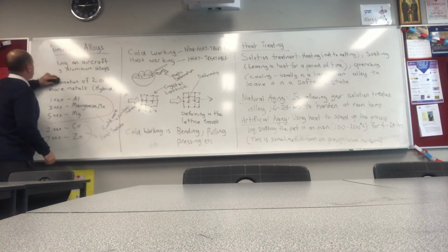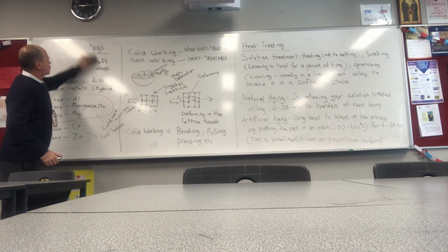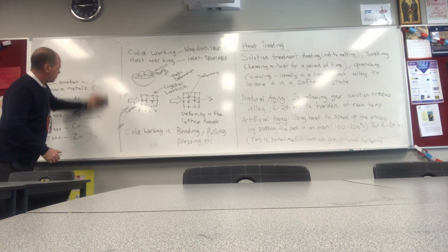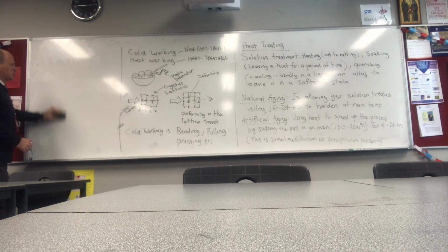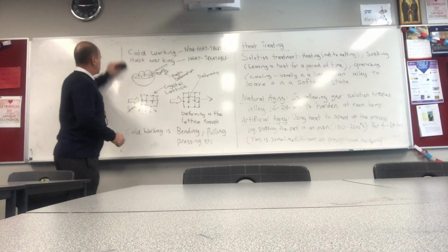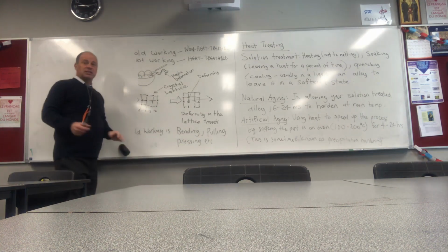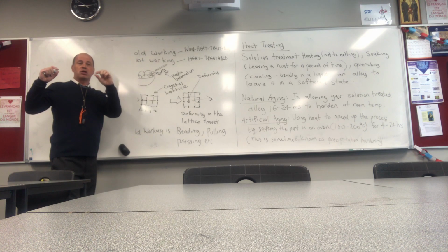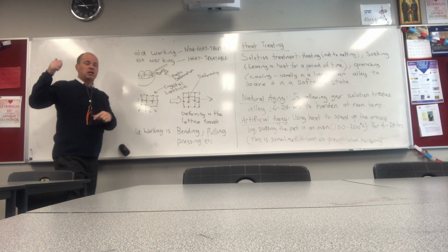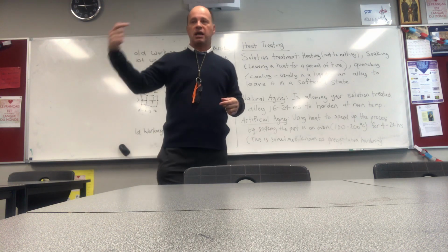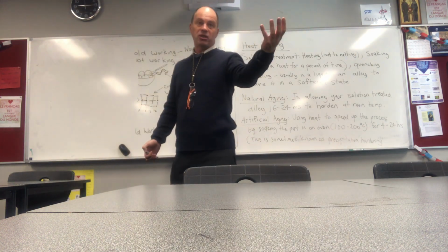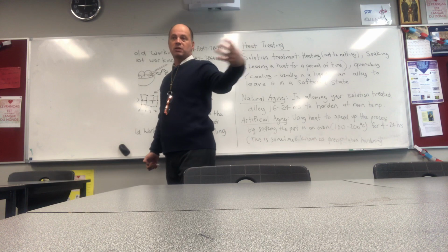Because yeah, it's a lot of information. It's a bit of a trade-off. Obviously, if you're really good at remembering numbers and codes and everything else, if you can remember the 4-digit code, in your notes there, they actually tell you that each of the alloys has a code. Okay, and you can read the code, and you can say if it's heat treatable or not heat treatable, whether it's aged naturally or aged artificially, how hard it's been aged to, like the actual time it's spent in the oven.